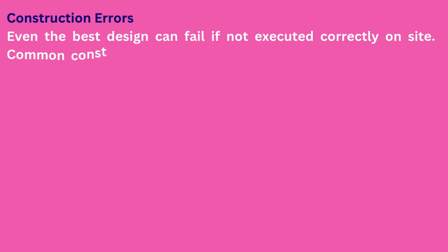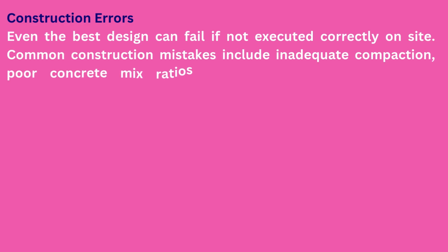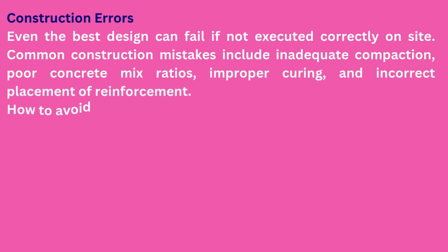Construction errors. Even the best design can fail if not executed correctly on site. Common construction mistakes include inadequate compaction, poor concrete mix ratios, improper curing, and incorrect placement of reinforcement.